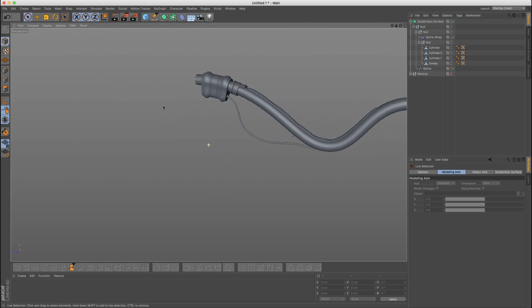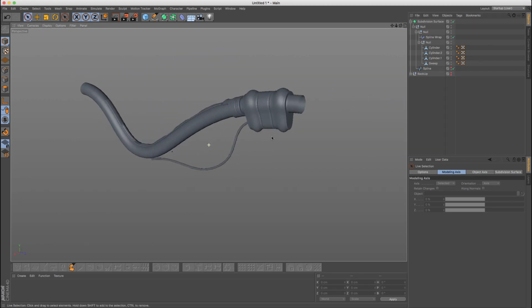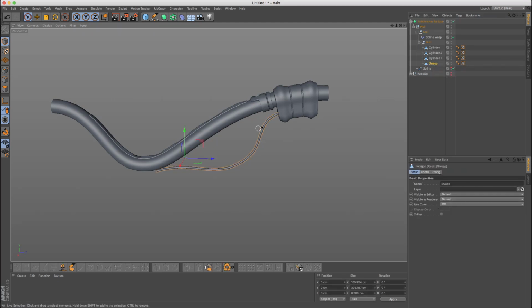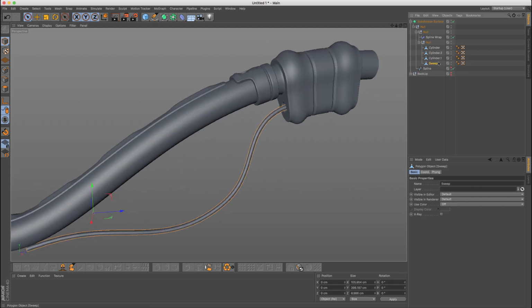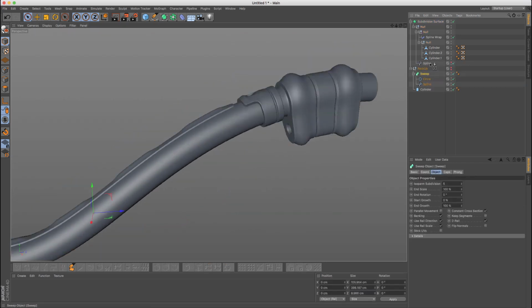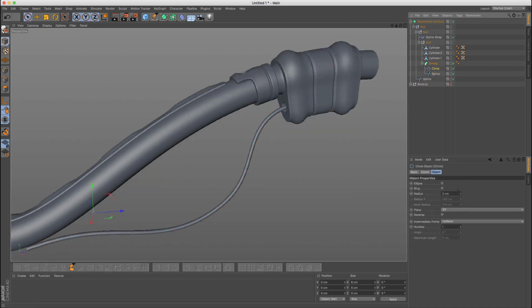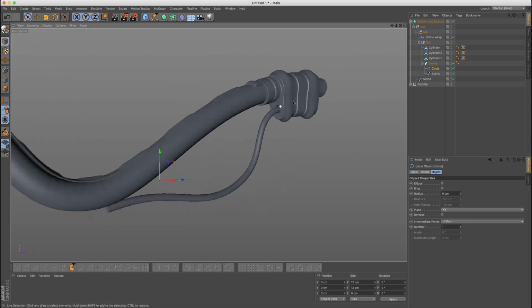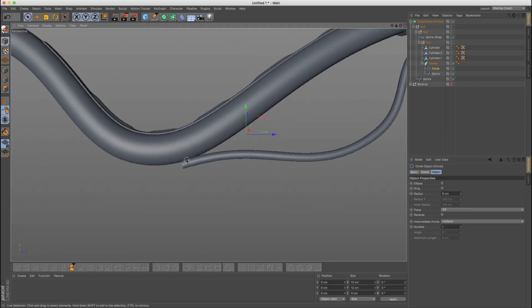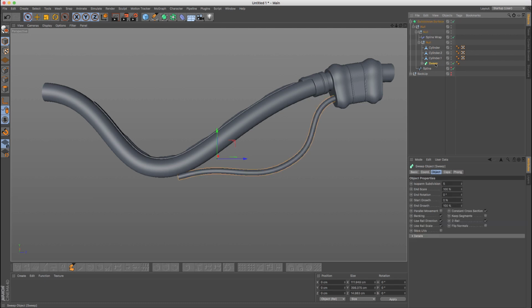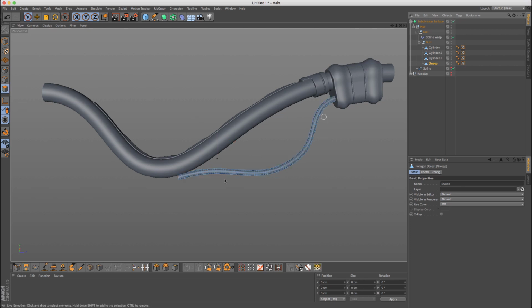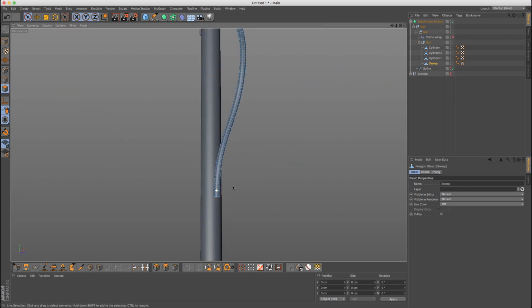And if we go into a spline wrap, this is what we have. So let's now come here into our where we have, actually now is the time when we need to use our backup, because I kind of spoke too soon. So let's put it here and increase the radius a bit, something like that. It's working a bit better. And now we can subdivide, actually make it editable. And let's see what kind of detail we can create there. Actually, we need to create a transition.